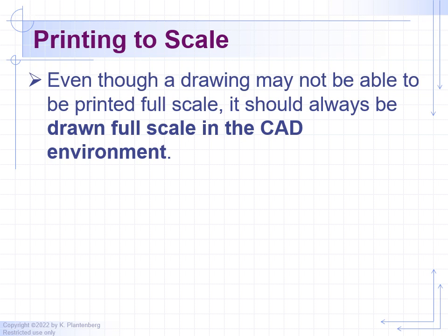Very important that when you draw in AutoCAD, you draw things in full scale, right? So even though you plan on eventually, say, printing it out half size, quarter size, etc., when you draw the object, you draw it its full size, full length, etc. So if something's an inch long, you draw it an inch long. If something is 50 feet long, you draw it 50 feet long. You worry about scale when you're outputting it, whether you're printing it or sending it to, say, a PDF. But when you're drawing, you always draw full scale, 1:1. Right? That's very important. That's how all our dimensioning works, because we just pull our dimensions directly off the object, so they have to be the right size.